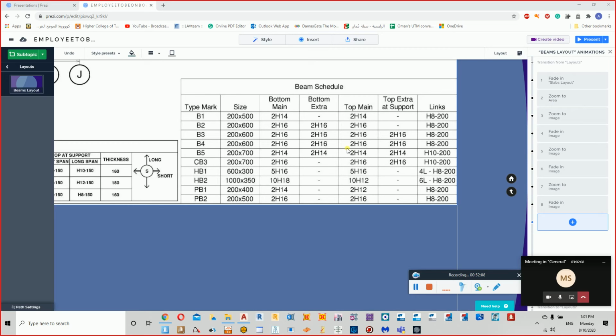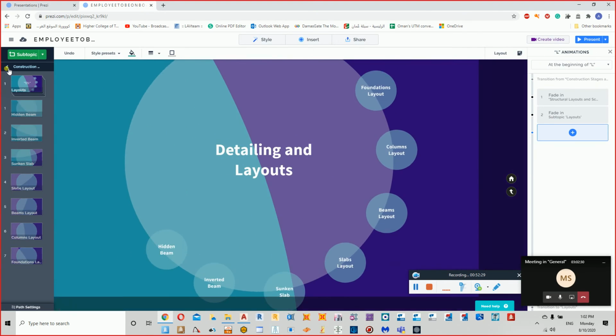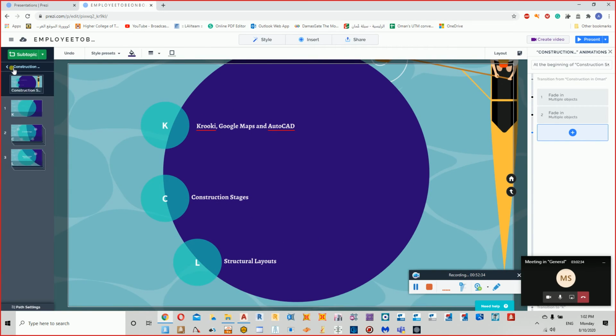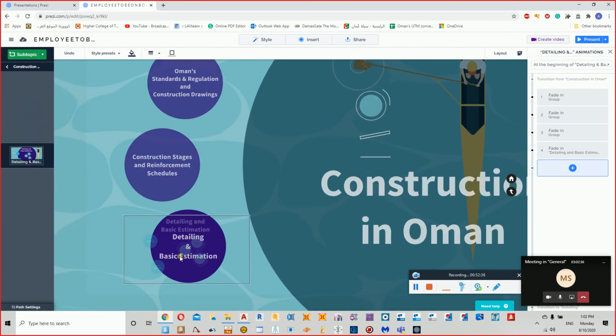Now what do we need to do? We need to supply one reinforcement from the beginning till the end for the top bar. If it's sufficient, then we are okay. If it's not sufficient, then at the peak, which is the center, we need to supply extra reinforcement. In order for you to understand that particular thing, we are going to go for the detailing. I'll just show you the detailing. Although it's tomorrow's session, it will make you understand a bit more.